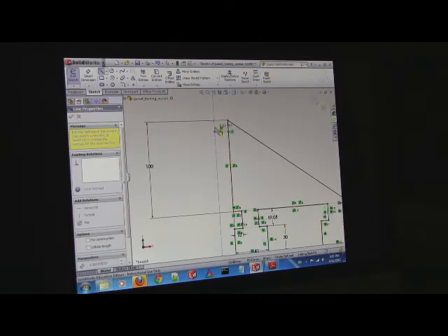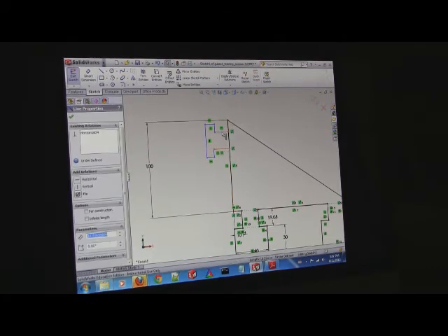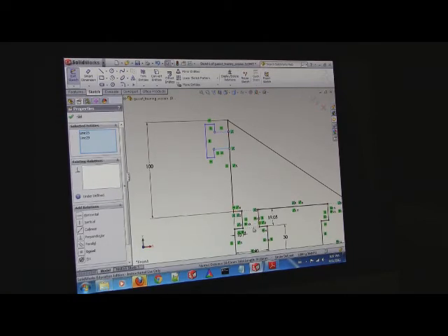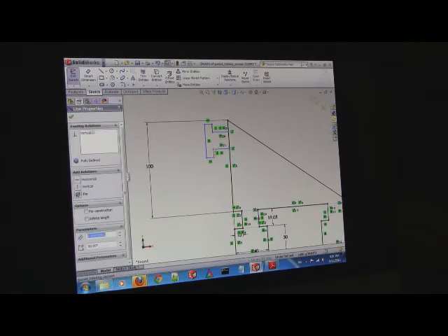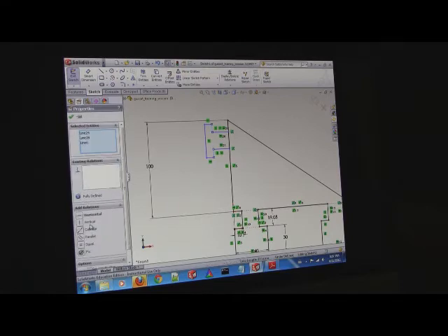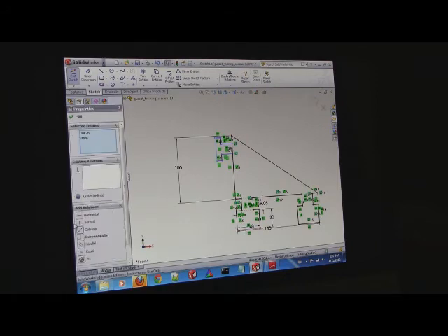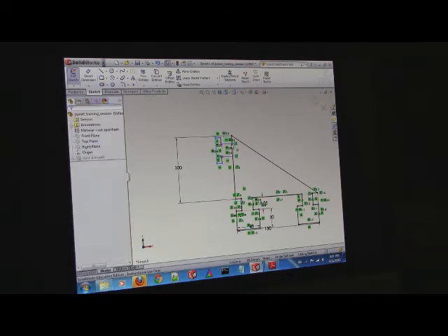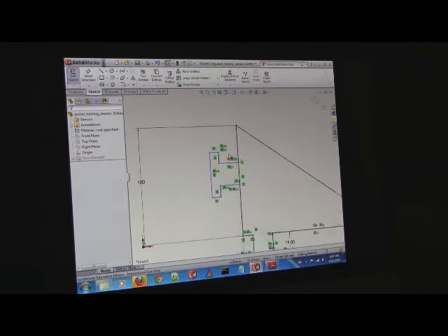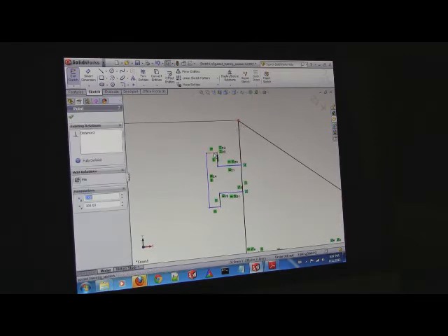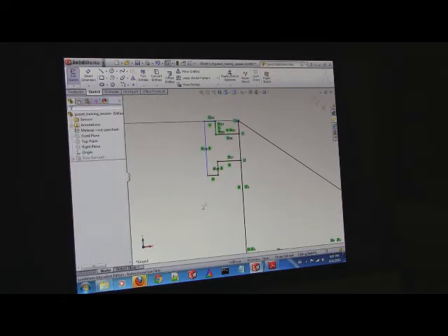So do the rough shape again. You guys are going to be experts at clicking by the end of tonight. Then we're going to do the exact same constraints and base them off of the dimensioned one. So this line and this one, 19.05 equal. This line and this one, 10 equal. This one and this one equal. And then I want you to press the top vertex and this line and press coincident.